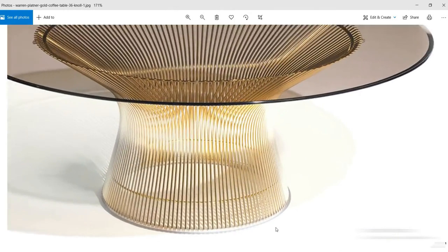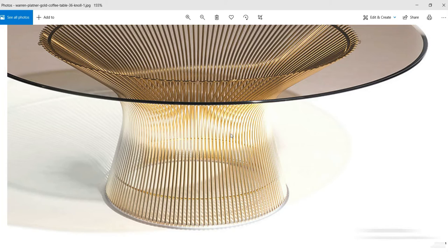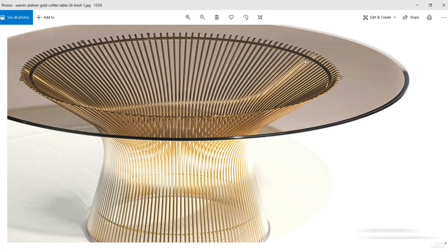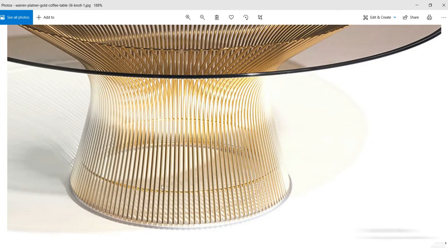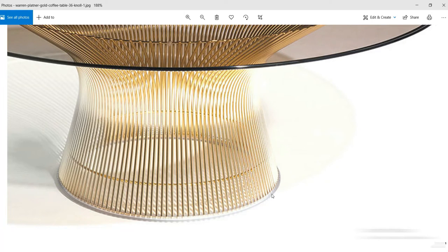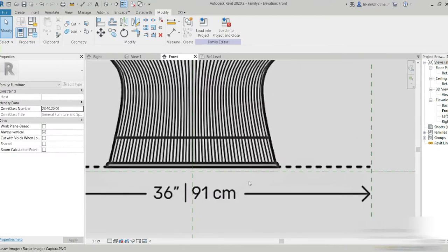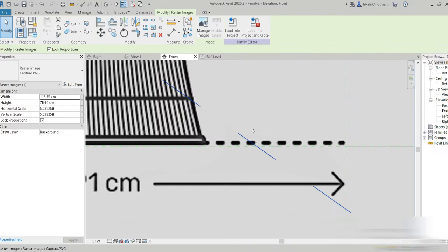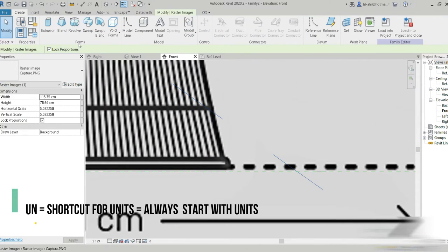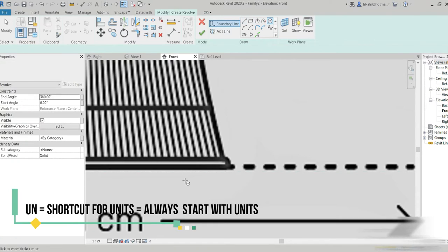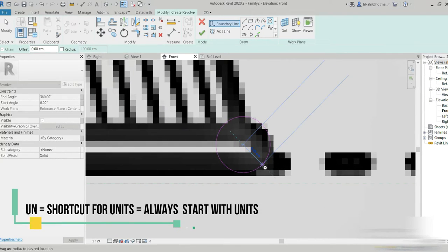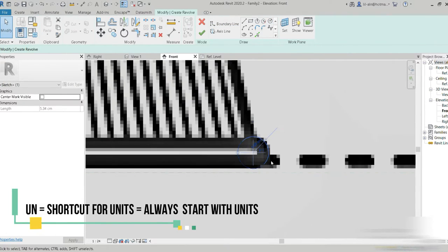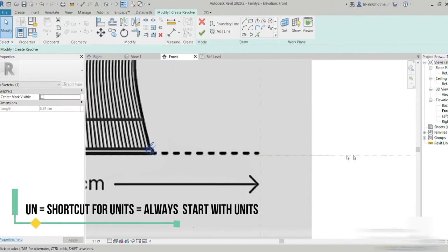Okay, fine. Now this is the reference image that we have. So let's start with our modeling. The first thing is we have this strip facade, which is golden, and we have this strip right here. Let's call this the revolve, and we have the second revolve right here, and we have the third revolve, which is this white sort of a circular shape. So let's first of all quickly draw that, and all right, now it's better. So the first thing is that circular revolve that you have. So let's choose the Revolve tool and circle, and let's go for, I think this is fine. So let's adjust it a bit down, and this is our reference line.